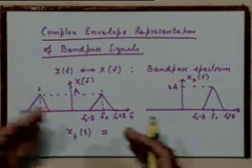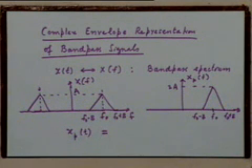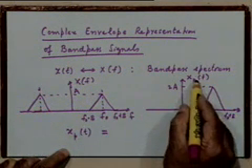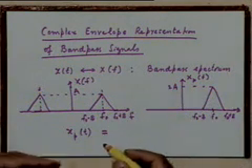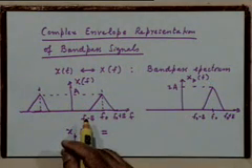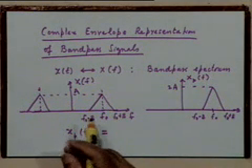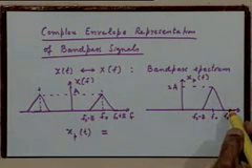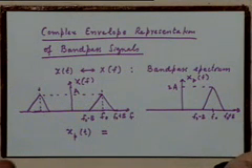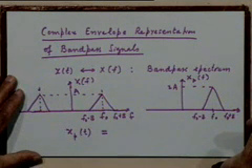And how do you do frequency translation? By f0 only, by multiplying it with an exponential, right? So therefore it stands to reason that I could represent this xpt as a frequency translated version of some low pass signal whose spectrum is this, right? Will that be symmetrical? May not be symmetrical. That will depend on whether this is symmetrical. Therefore that signal may not be real, it can be complex.